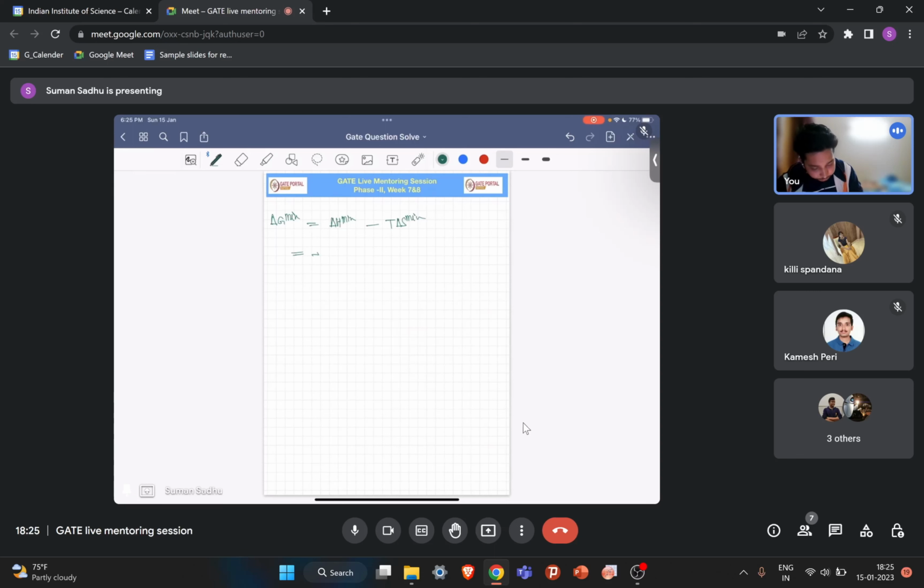Delta H mix is omega XA XB, and T delta S mix means RT times XA ln XA plus XB ln XB. This is delta G mix, and G of solution is G of mixture plus delta G mix. G of mixture means physical mixture. Okay, now let us draw the free energy versus composition diagram.